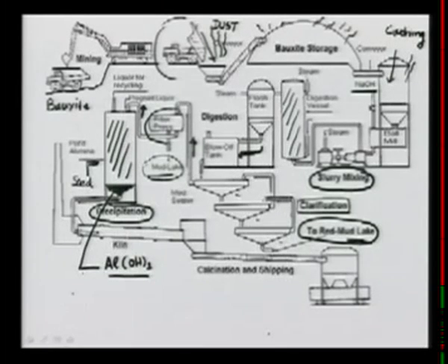All right, now in the process what we have got is the aluminium hydroxide, and recall where we want to reach. We want to reach the alumina, and what was alumina? Al2O3. So now we have to apply something so that we produce the Al2O3, and whenever there is a hydroxide and you want to get into the oxidized state, what we do is the process called calcination.